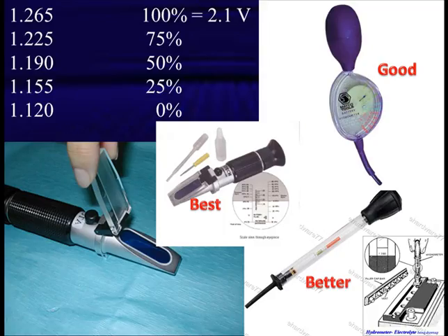If one of those little 9-volt batteries is discharged and you try to charge it back up, no way is it going to be possible because it has to go through the other batteries to get there. All of these cells are hooked in series. So when I have one of these that's well out of line in state of charge, that battery is going to be bad. If I'm around 1200, I cannot trust the 1200 cell when I've got others at 1265. The battery is going to fail soon.